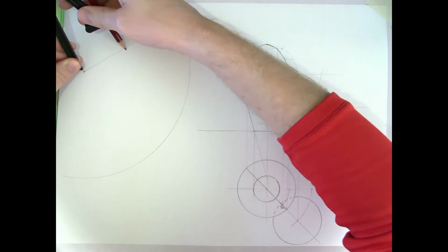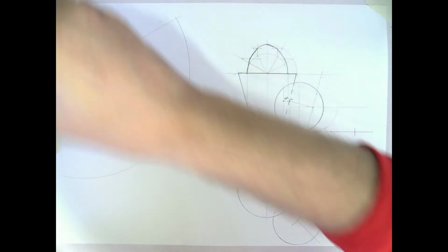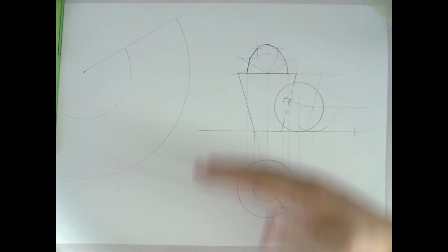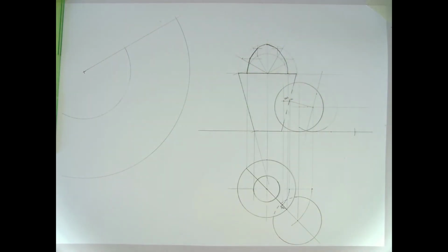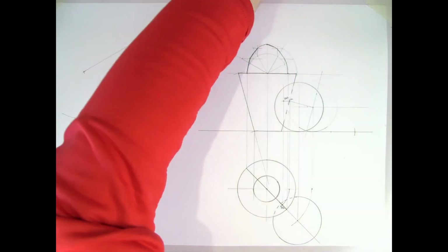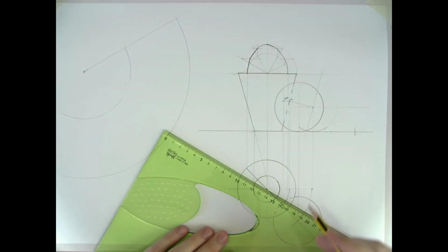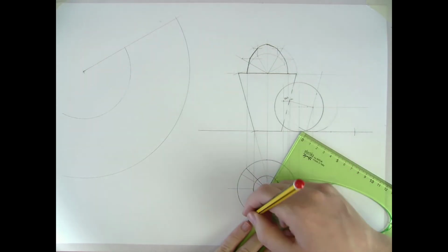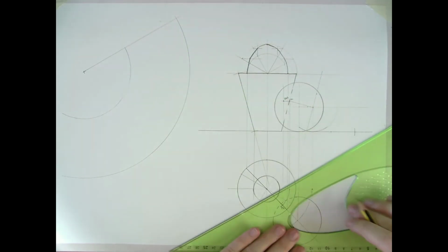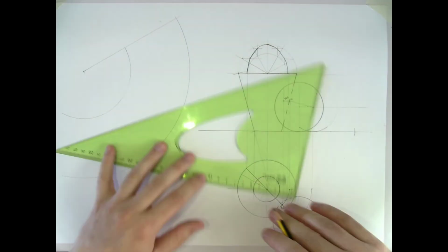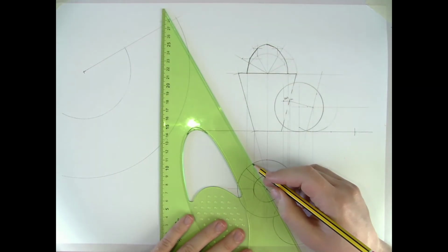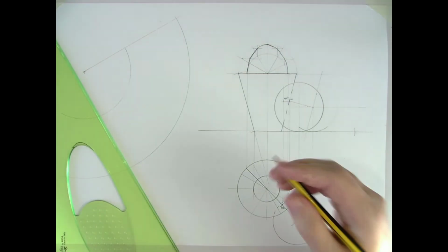And I can draw in this arc. So this much here is that part of the cone. Now we just need to figure out how long the thing is. To do that, we're going to divide the cone up in plan with our 60-30 degree set square and take approximations for the side length. So divide it up 60-30. And that breaks my cone up into 12 parts.